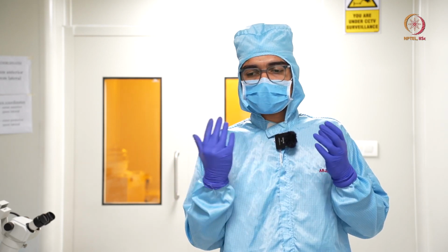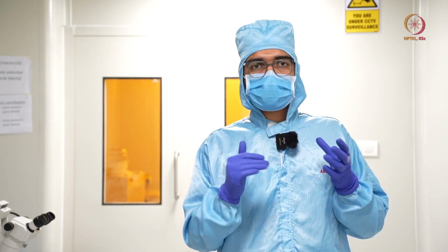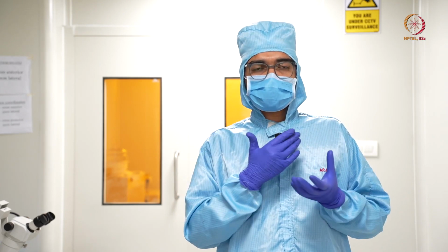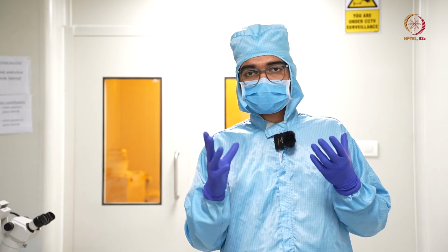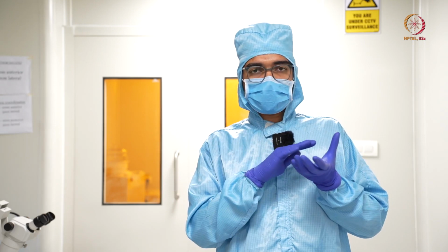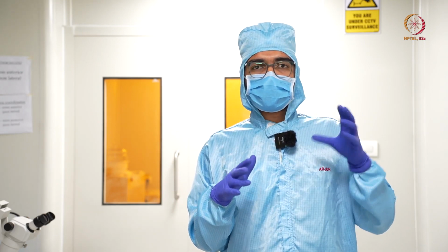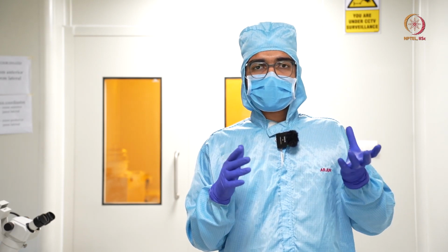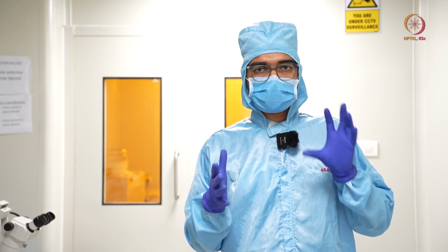So consider this like a fluid kind of material, which is like a paint. Assume photoresist like a paint, which we coat on a substrate using a process known as spin coating. Okay, so we have a thin fluid coating over the substrate that we need. Now we dry it, so that's known as soft bake, or pre-bake. So that's one step.